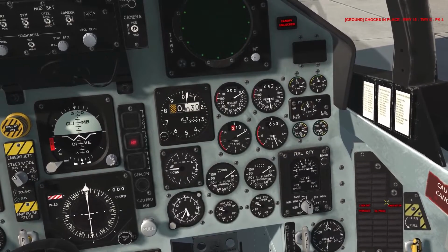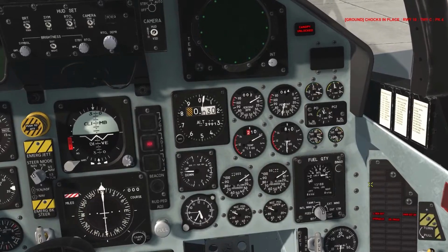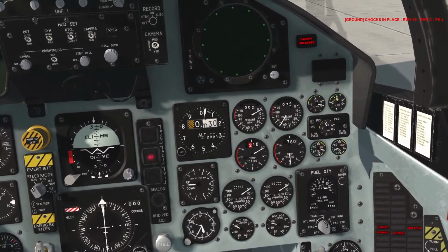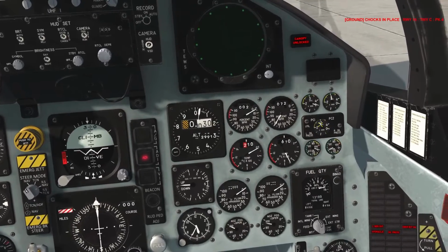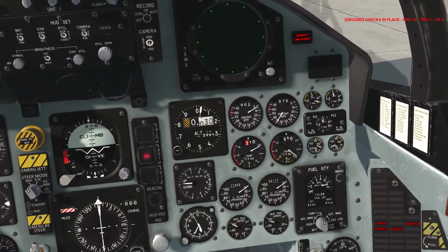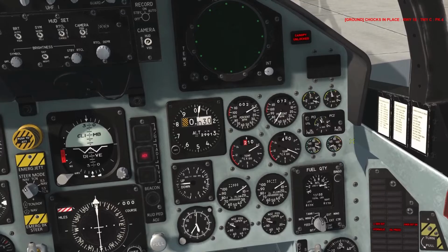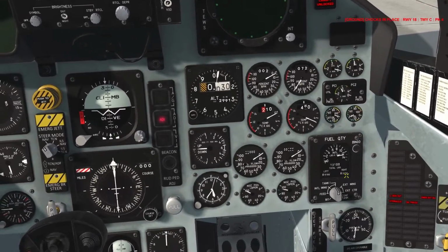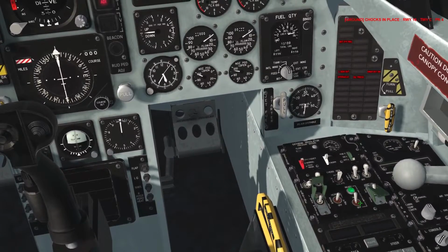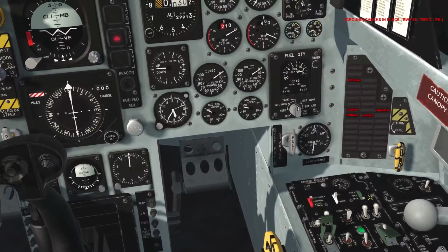So the generators come on. We've got some lights happening. The right engine powered hydraulic system is in the green, as is the utility, and we've got the temperature stabilizing below 640. That's a good start. So the JFS has gone back to ready, indicating that the left engine is ready to be started, and verify that the emergency BST light is on.